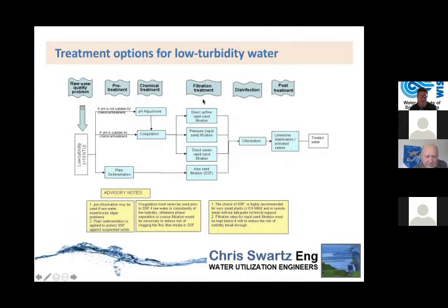For turbidity or filtration that you can use, there's 4 different types: direct, upflow, pressure filtration, direct series, slow sand and so on. You'll see there's not normal rapid gravity in here because we're looking at low turbidity water. So you can do that by other processes that you don't have to first add some turbidity through clays and so forth.